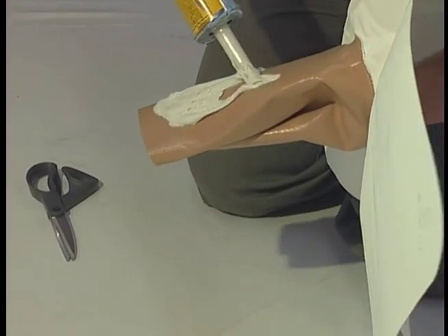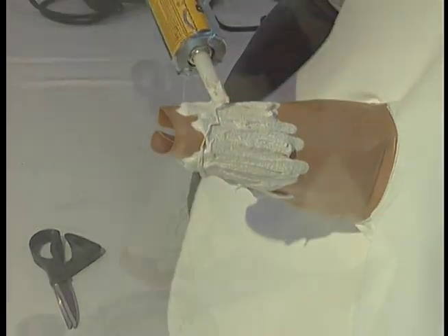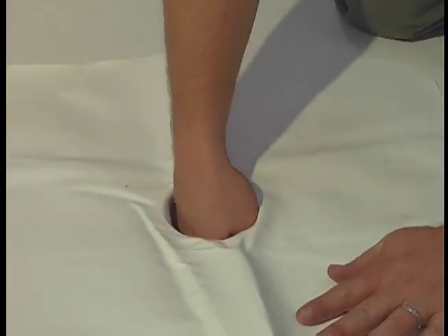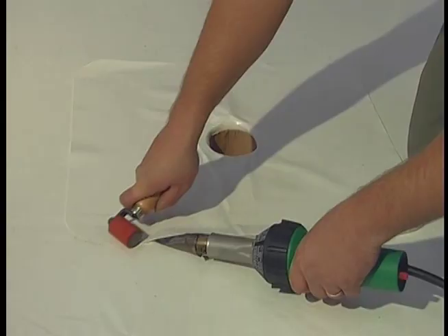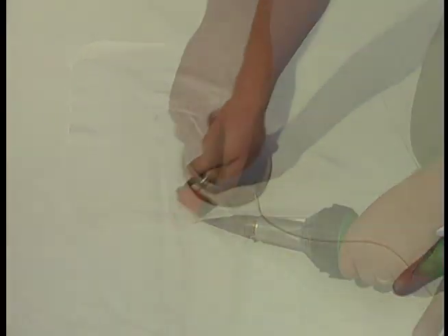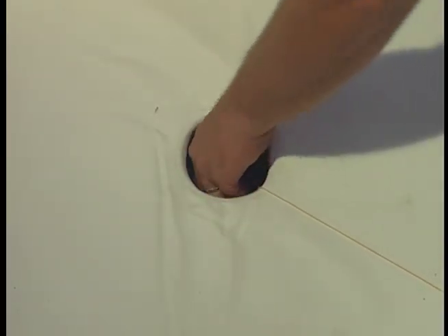Apply a minimum of half a tube of caulk to the bottom 4 inches of the drain boot sleeve. Insert the sleeve into the drain and adjust the drain into the proper position. Heat weld the skirt to the deck membrane, being sure to make a minimum 1 1/2 inch wide weld. Insert the drain rings to the same location as the caulk, as far down the sleeve as possible.